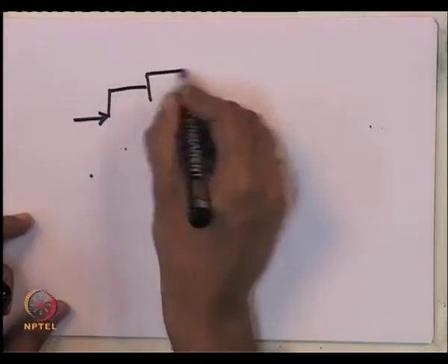So, you can say that if your system is working well, it is stable. That is of course not something which I have proved. The point is that if you have designed your feedback control system well, it is stable. Then in steady state, if you are using a PI controller, a controller which has got an integral component as shown there, the steady state error is driven to 0. Is that okay? So, just to do a quick example, suppose I have got a PI controller, say this has